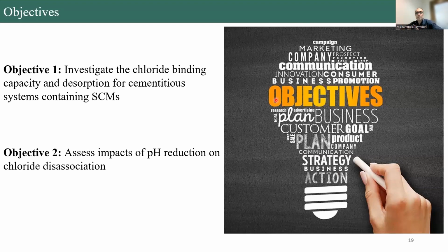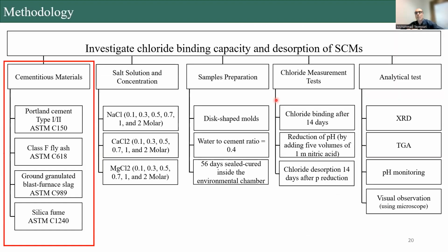the pH measurement matters. We cannot measure the pH for a structure that has already deteriorated, right? So we need to take into consideration, for example, that for a fully carbonated structure, the pH is around 9. So in this investigation, we played with different ranges, but at the end, I will present only the specific range that is practical in the field. So these are our methods.